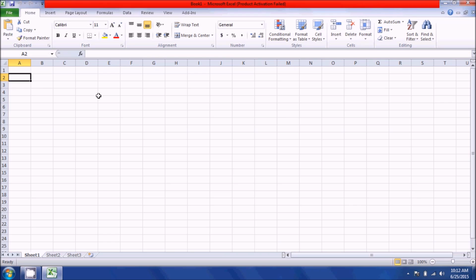We had 9 different trials in LabVIEW, so I'm going to make a little table below trials. The next thing we need is our length, LS, in meters, and our mass in kilograms. Then we need to calculate V0 in volts, and we're going to have to back calculate that using the strain. So the next column we need is strain, and that's just strain itself.